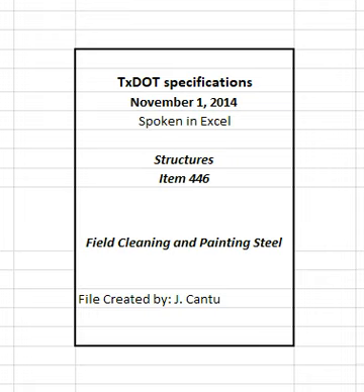When using abrasive blasting equipment equipped with negative pressure able to contain all blast refuse, demonstrate, for approval, the equipment's ability to contain all blast refuse. When using hand tools for spot cleaning only, provide a system that will contain all removed paint, rust, and other debris. Place an airtight membrane below the member being cleaned to collect all falling debris.